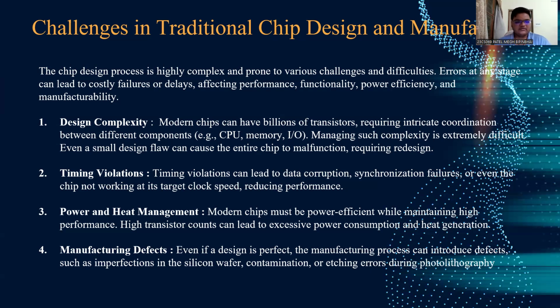Then, we also have to discuss manufacturing defects. Let's say a design is perfect and the manufacturing process has begun. It can introduce defects such as imperfections in the silicon wafer, contamination, or etching errors during the photolithography process.